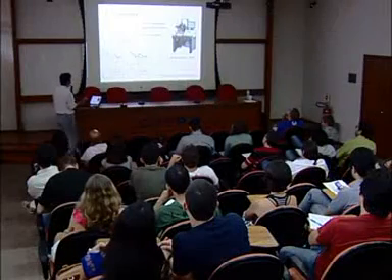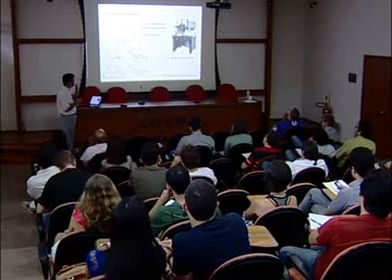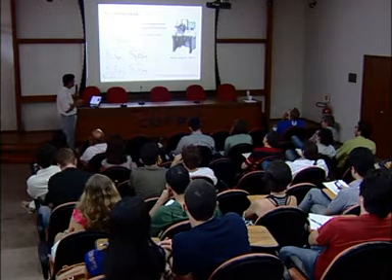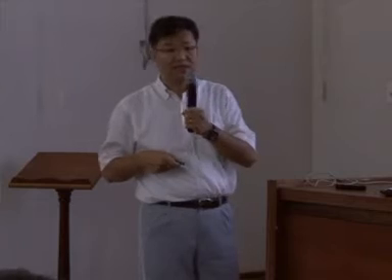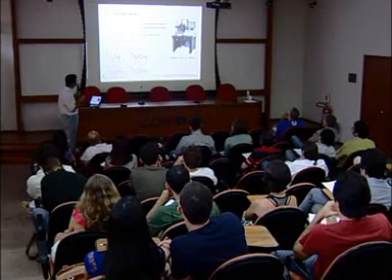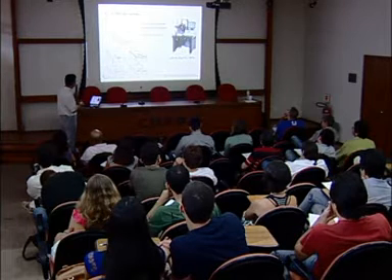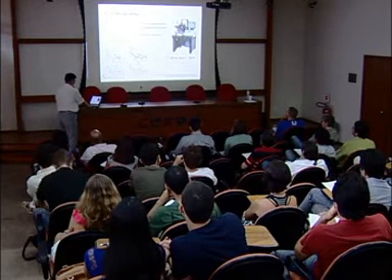And this machine is a lithography machine called MA6. UV light is exposed onto the wafer, and the pattern is transferred onto it. Then, using the pattern, we can etch out the oxidation layer.